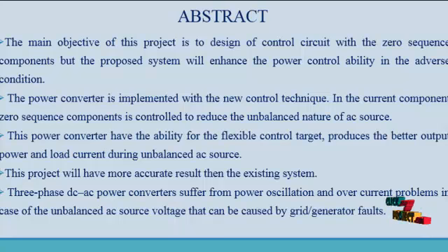It is concluded that by introducing proper zero sequence current controls and the corresponding circuit configuration, the power converter can enable more flexible control targets, achieving better performance in the delivered power and the load current when suffering from unbalanced AC voltages. And the main thing in this proposed implementation is that we only provide the given flow diagram and the corresponding waveforms.